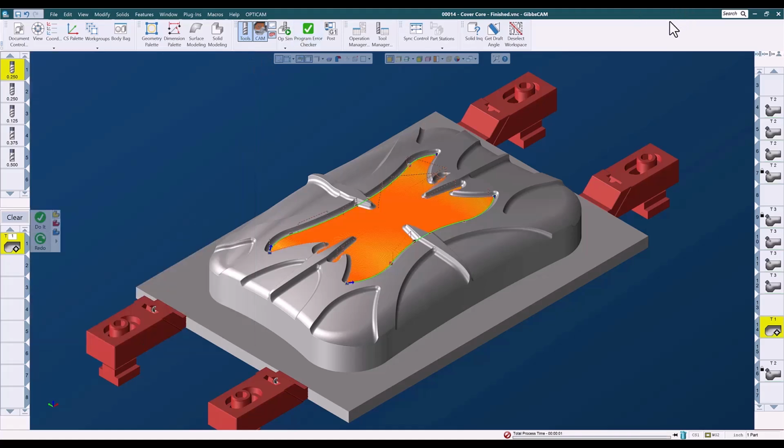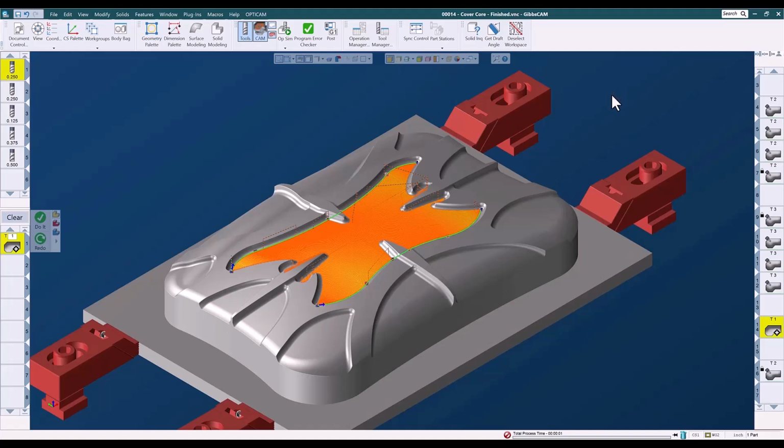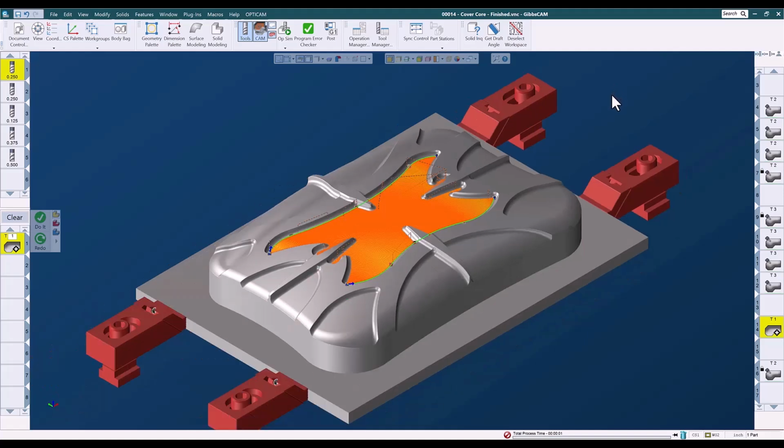These saved processes capture the settings for the tool use, speeds and feeds, depth of cut, really all the information about the toolpath except specifically what to cut. And if the tool is not already in your tool list, the process will build it automatically. Over time, saving and utilizing these processes can really streamline your programming, as well as standardizing many of your processes to provide a greater degree of consistency from one job to the next, or for that matter, from one programmer to the next.